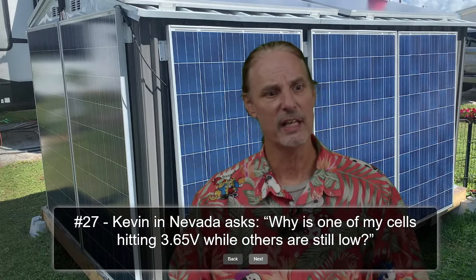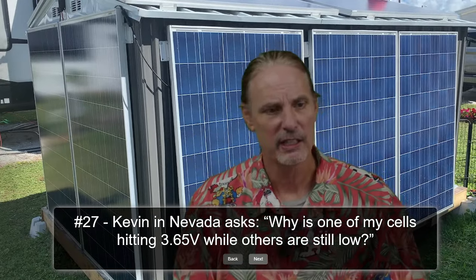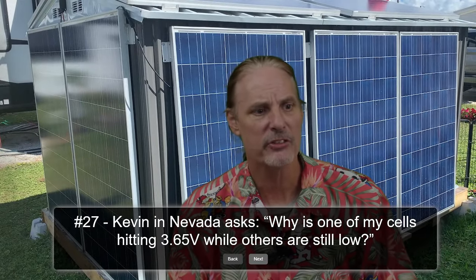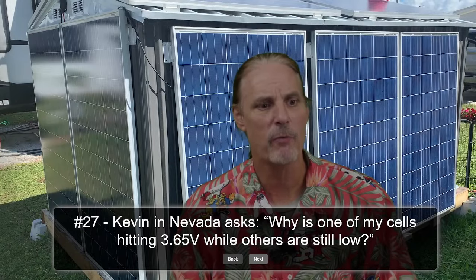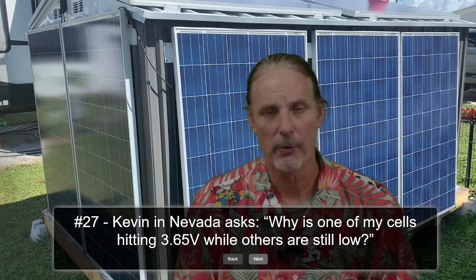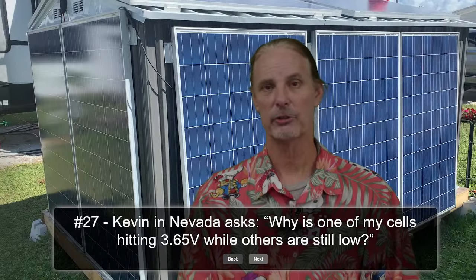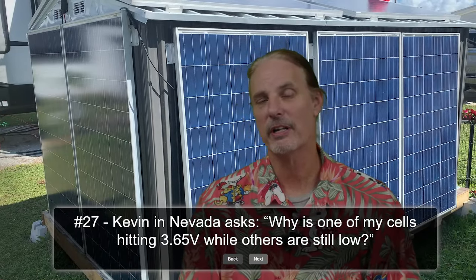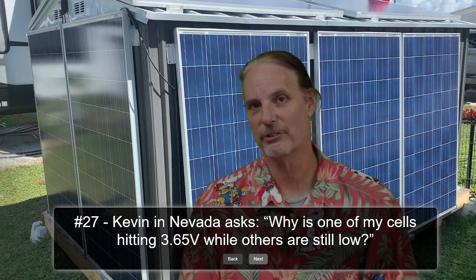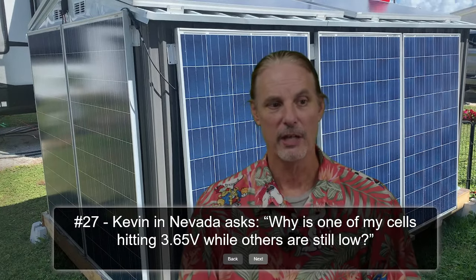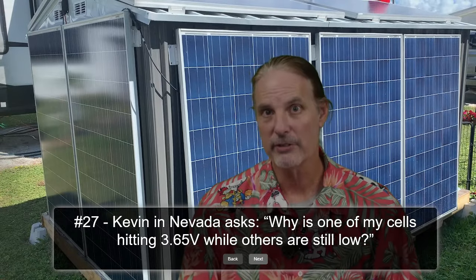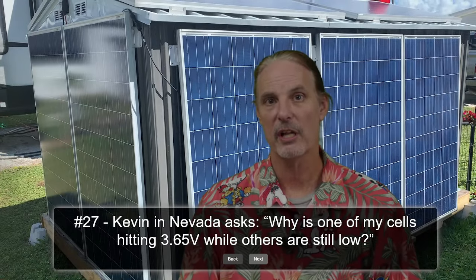Kevin in Nevada asked, why is one of my cells hitting 3.65 while the others are still low? And this goes back to your state of charge not really matching what's going on. And this is kind of the whole topic of this live stream today. Your battery is out of balance. And because your battery is out of balance, that one cell is there.